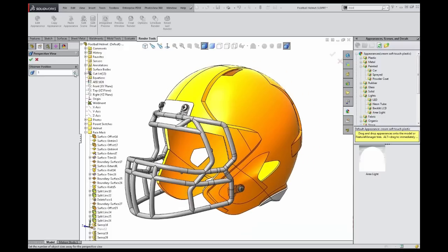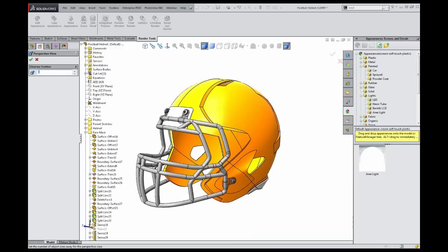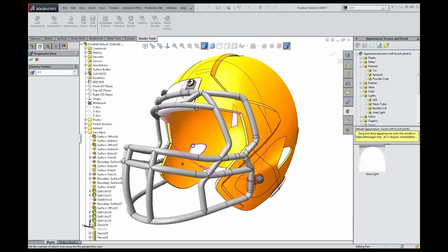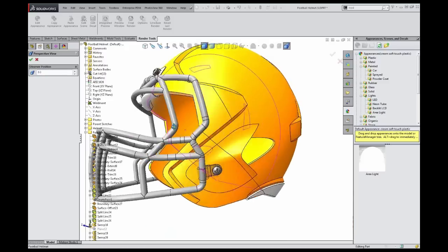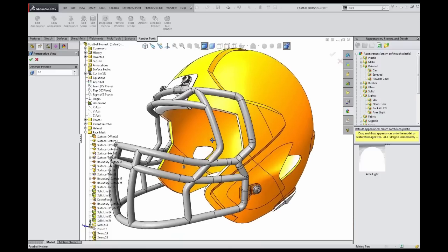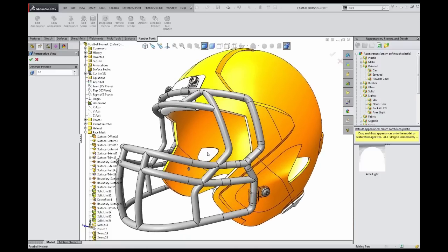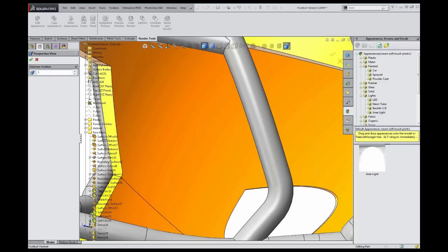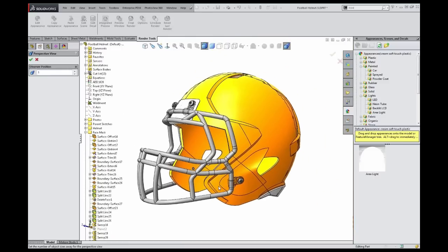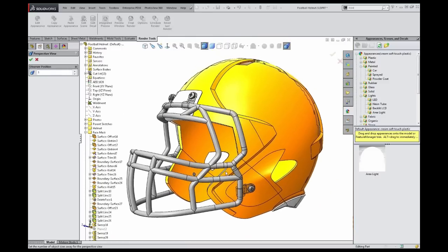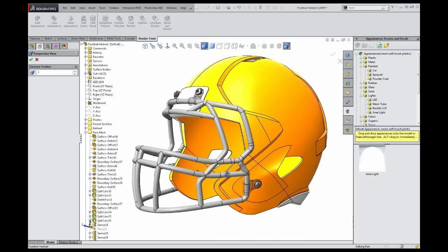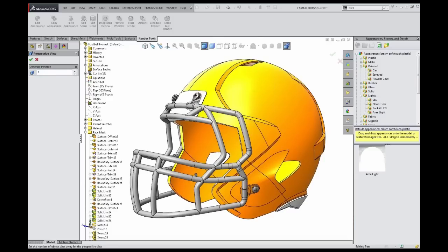The smaller I make it, the more drastic it's going to be. I could actually go all the way down to 0.1 if I wanted to, and you could see this is a very, very drastic, pretty cool look, as if we held the camera directly up against or just a few inches away from the subject matter. I'm going to crank this up maybe to 1 so that the angles aren't that drastic. But you can see how it gives it a much better look than having no perspective whatsoever, and better than the initial value of 3 as well.